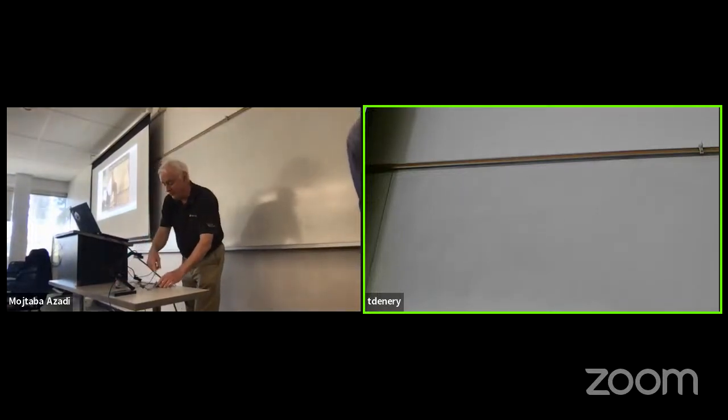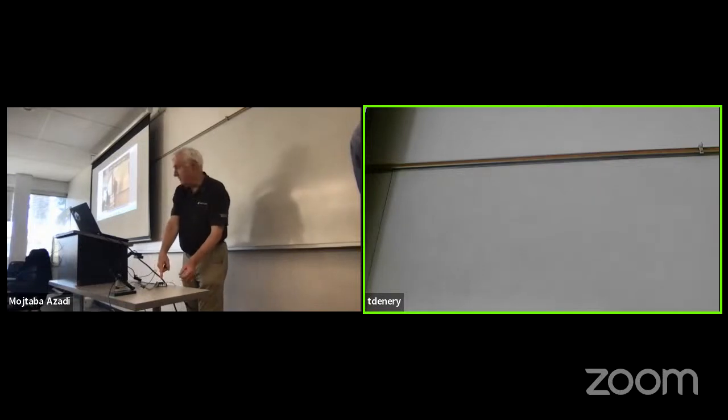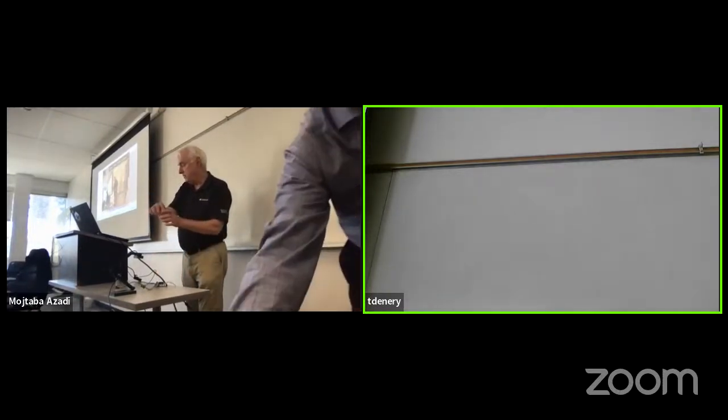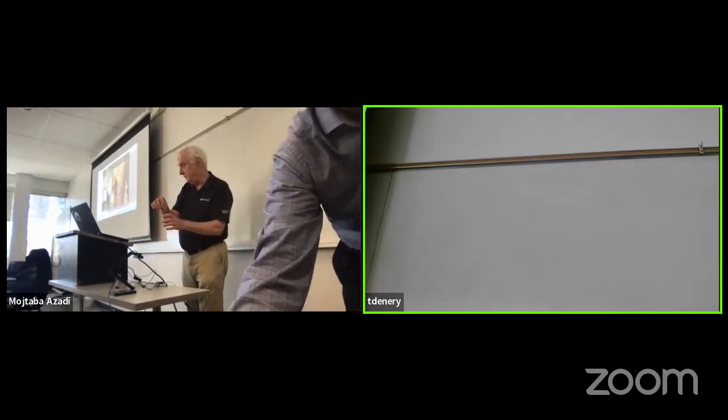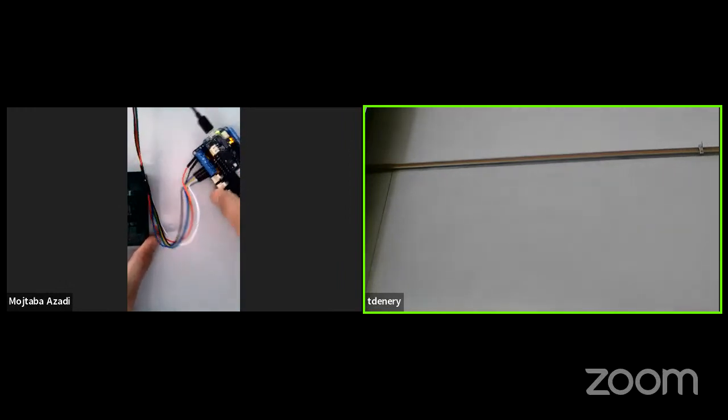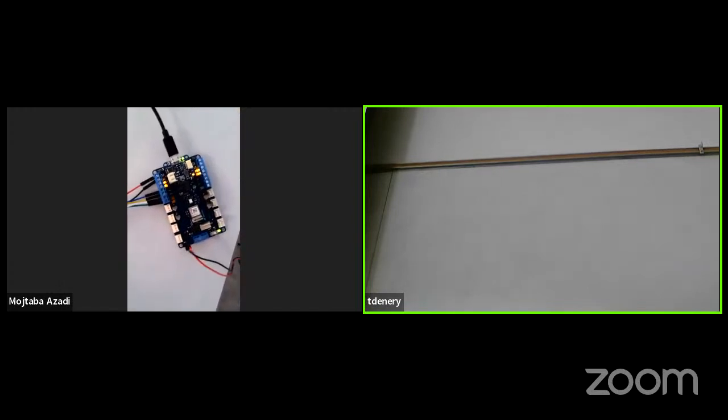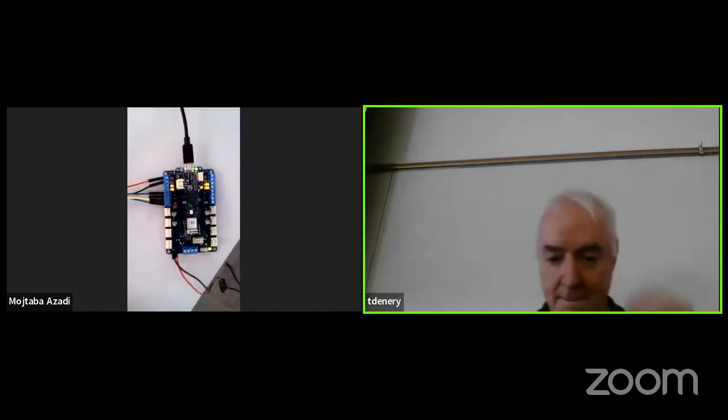So we're going to do some Arduino stuff. What I have here is a Maker Wi-Fi 1010 board with what they call a motor shield on it. The motor shield means I have access to an H-bridge, which allows me to use pulse width modulation to adjust the voltages that are delivered to the motor. It also has terminals I can plug into to access the encoder. And the encoder will tell me the angle that we're going to move at.